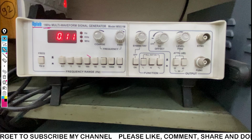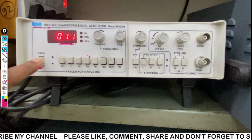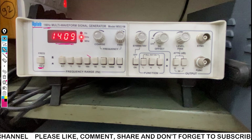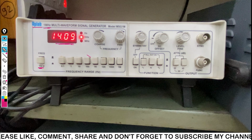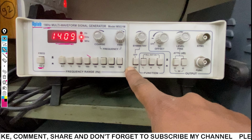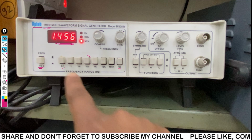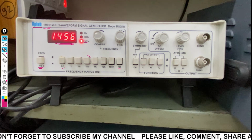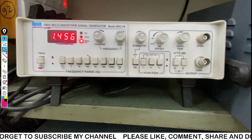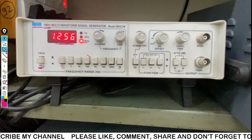You can see, by pressing this button we can change from voltage to frequency. See here, it is now a frequency. Previously if I pressed it, it was a voltage. Now you can see these are the frequency ranges starting from 0.1 hertz to 1 megahertz. If I press 1 megahertz, it will show megahertz, while if I press the lesser range, then we'll have very less frequency.